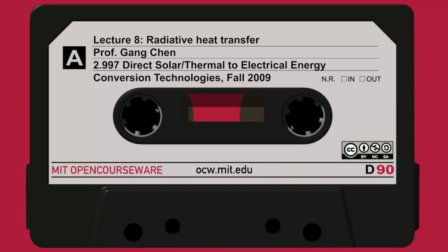And so if this selective surface is a 1, 0, and I design the selective wavelengths here, if you look at it, this blackbody emission reduces rapidly. Now I have to remind you of Kirchhoff's law. When I say in this spectrum the absorption is 1, I also mean the emission is also 1.